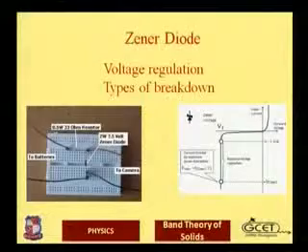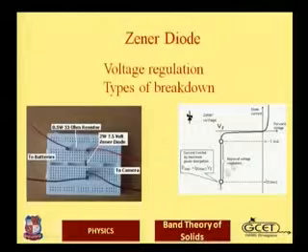One can have the Zener characteristics in the slide. It is one and the same as we have seen on the paper. The Zener voltage is here. It is actually the breakdown voltage, and the region of voltage regulation can be seen after the breakdown voltage, and this current is limited by the maximum power dissipation. The maximum power which can be taken by the Zener is IZ max into VZ, and of course the forward characteristic is one and the same as the simple normal PN junction diode.